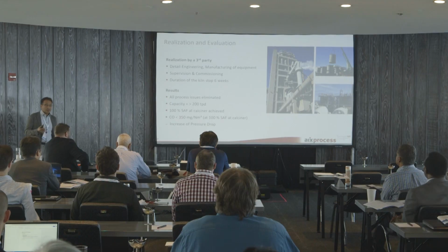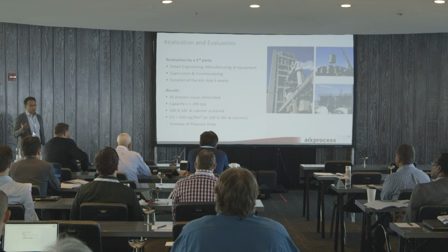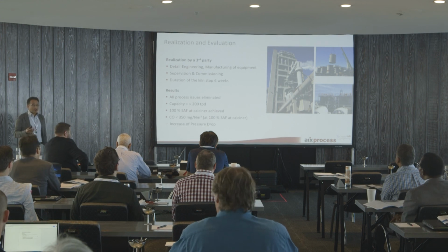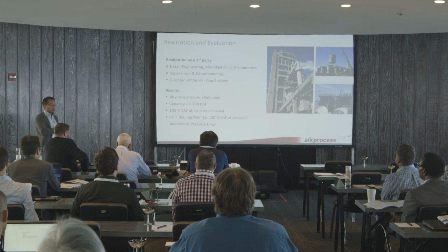We could increase the capacity. Now the secondary fuel rate is at 100%. So this is one goal, and we still match the CO emission. So this is really a success story. All the engineering was done up front, so there was no trial and error, and the duration of the stop was just 6 weeks. So this is a rather typical stop during summertime, where they typically do the revamping. So it is quite obvious that CFD really helps here to avoid trial and error in the field, and do it just virtually.